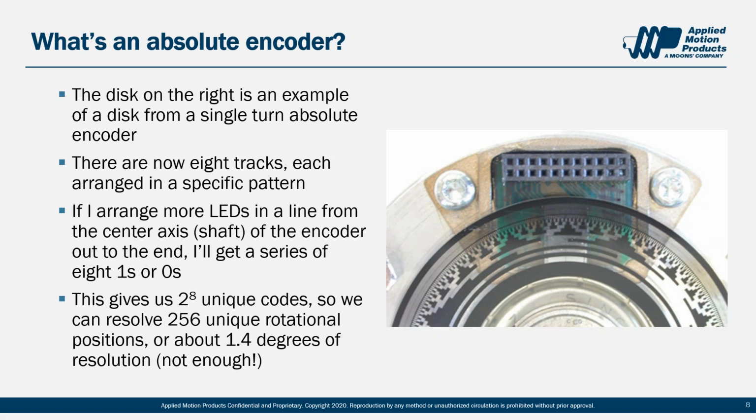But even with all the resolution in the world, this disk can only resolve the position within 360 degrees. What if you want to move more than that? You need to track how many revolutions the motor has gone from your initial home position. And to do this, we utilize something called a turns counter.